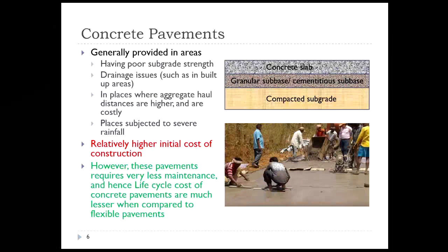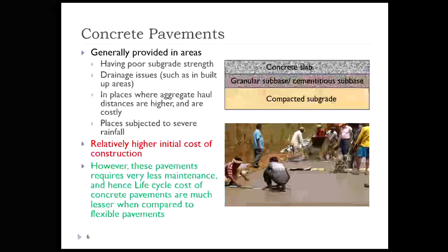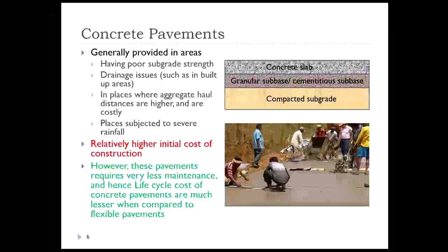So when we do a life cycle cost analysis, even in PMGSY, we tend to allocate money for resurfacing at the end of the 5th year, and budget for rehabilitation at the end of the 10th year.